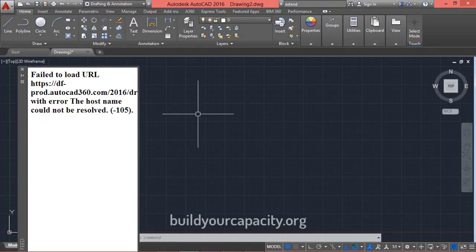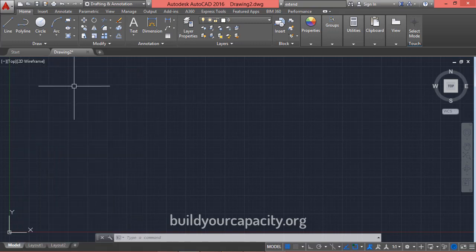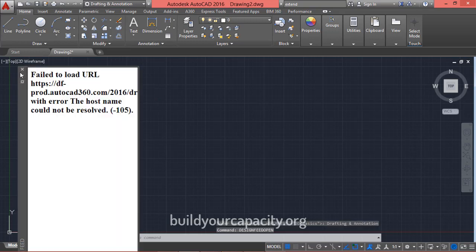Notice here that each time you switch to the 2D Drafting and Annotation workspace, the design feed automatically opens. This is because it is actually saved in this workspace. I will just go ahead and click this X here to close it. In case I require the design feed later on, I can just type design feed. Autocomplete gives me available options and I can click on design feed open. You can see that it is open. So let me close it again.